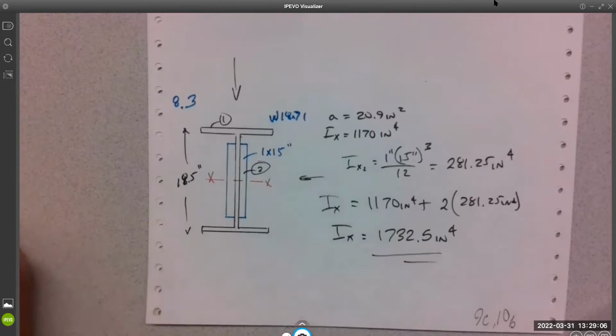So if you watch next time a big semi-truck trailer goes by you on the freeway, just look at that structural beam that's carrying it all. A lot of times that structural beam might even taper. But if it doesn't taper, you'll see areas of plates just welded on. Those are high stress areas where they need to drive up the inertia so it can carry that bending resistance in those spaces. It doesn't have to be full length. It can be just over a region.